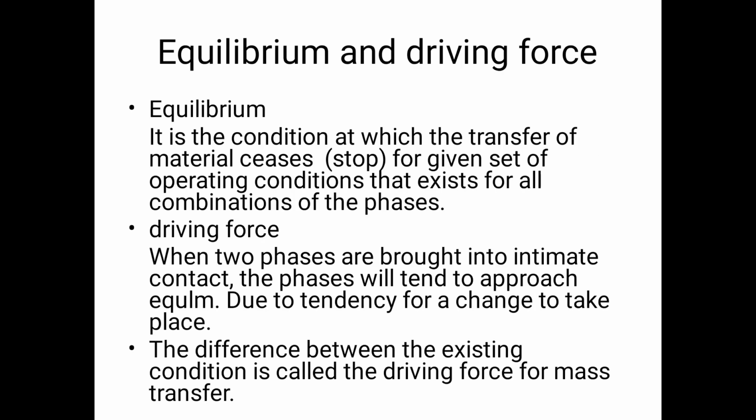And next, move on to what is equilibrium and what is the driving force. In a distillation column, these two are very important parameters. Equilibrium is the condition at which transfer of material ceases, that is, stops, for a given set of operating conditions that exist for all combinations of the phases. So equilibrium means once the process attains equilibrium, after that there is no change in that process. That is called an equilibrium process. What is driving force?